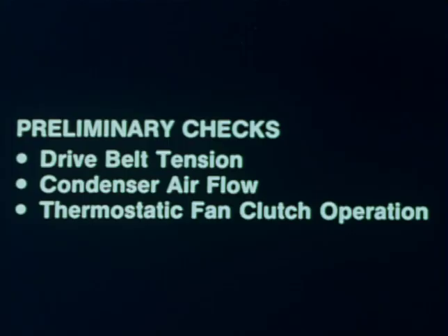Now that you are acquainted with the OTCC system and how it differs from other systems used in Chevrolet cars and light-duty trucks, let's look at some diagnostic procedures. Some preliminary checks that should be made when diagnosing an air conditioner complaint include drive belt tension, airflow through the condenser, and thermostatic fan clutch operation. Any one of these items can cause the air conditioner to operate below capacity.